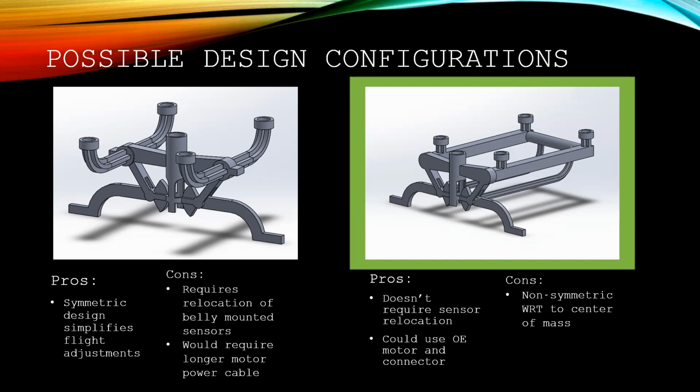The changes in mass distribution would ultimately change the inertial values with respect to rotation in all 3 axes. Fortunately, this information was attained through SolidWorks mass properties, which was then forwarded to Robert for him to input into the drone's properties. So due to the far less complex nature of the front mount design, this design was chosen to be further developed and improved upon for the eventual deployment onto the drone. The next step in the design phase was to design a subframe for the grabber to be mounted to, as well as for the landing legs to be attached to.